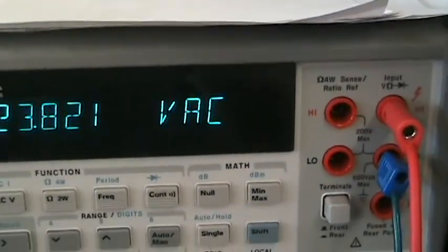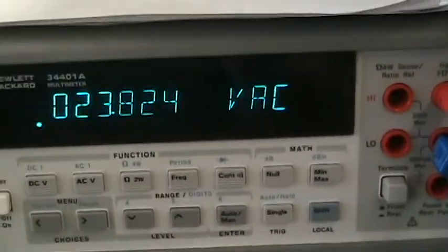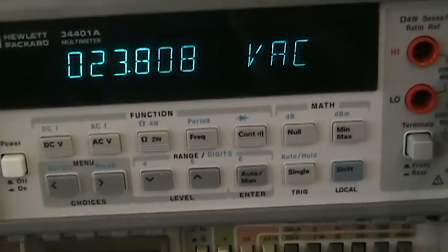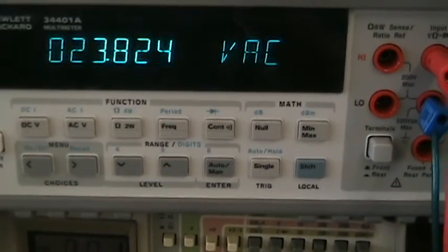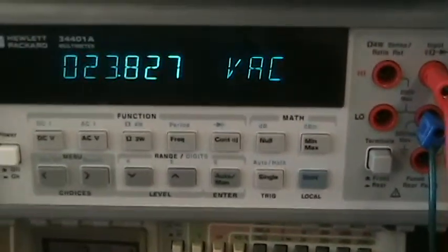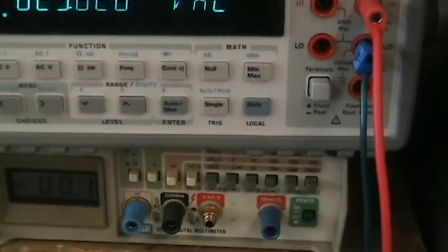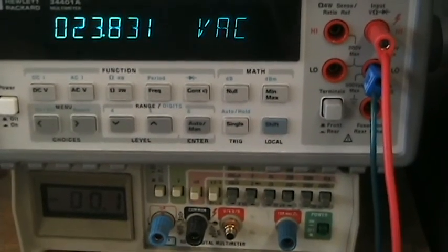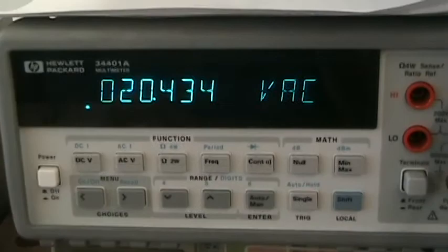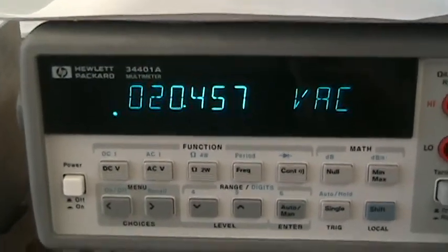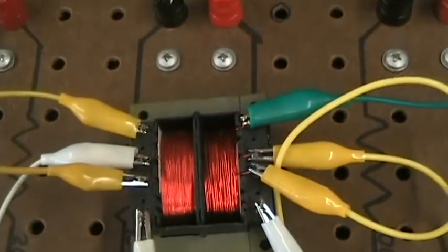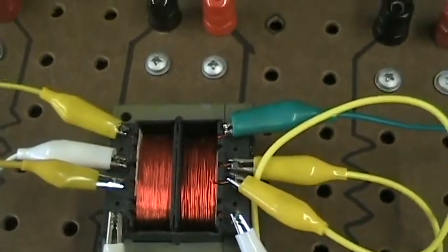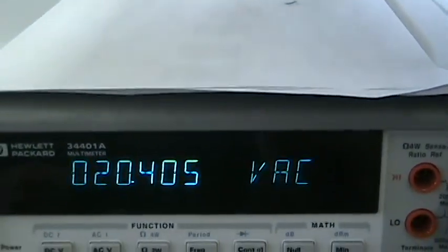The output voltage is very similar to previous. We have two windings now, but they're both 115 volts. Output voltage is 23.8 volts. Now previously we saw the voltage drop to 19 volts, so we'll see what happens now. And you can see that the voltage only dropped to 20 volts. It still dropped because of the loading of the resistor, but by using two windings instead of one, we're actually using the full capability of the transformer, and we get better voltage regulation.